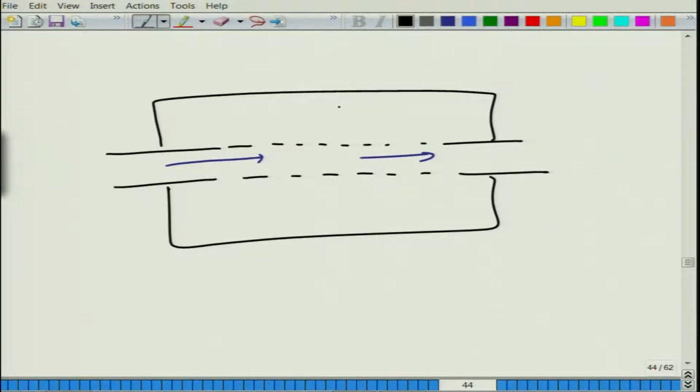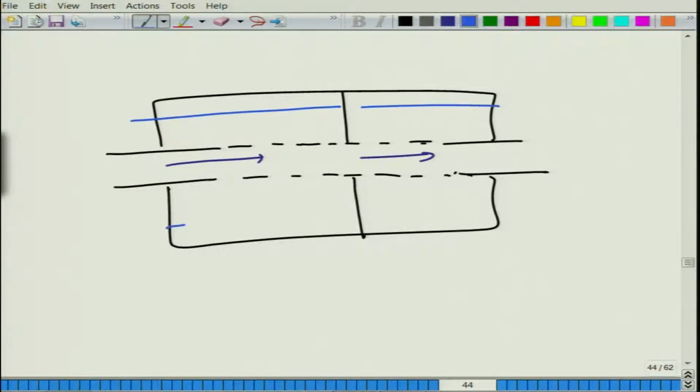For example, one can always put a plug here as we analyzed, or you can have a dual kind of configuration, with extensions or with partially perforated things, and then you can keep adding complexities like putting a dissipative lining, okay, and then the flow goes.